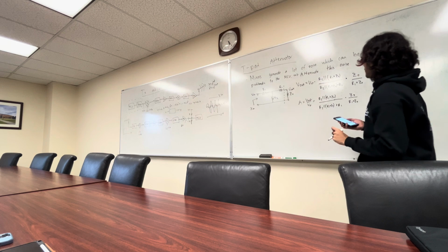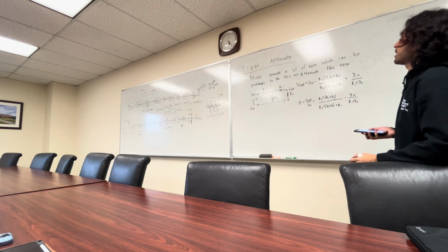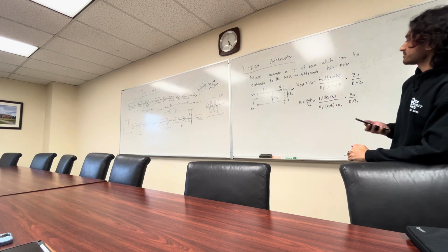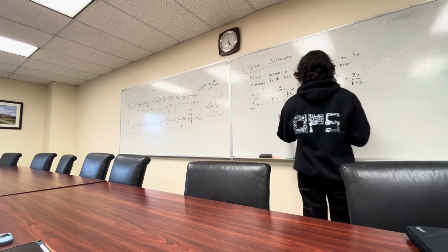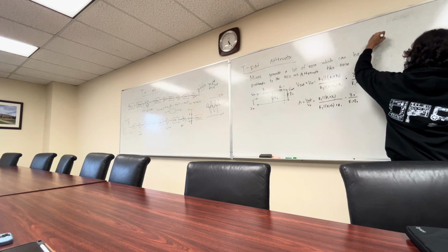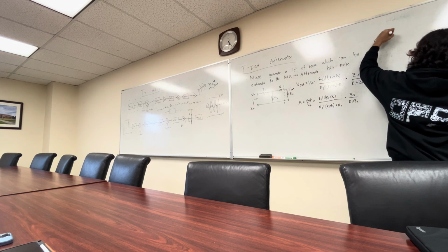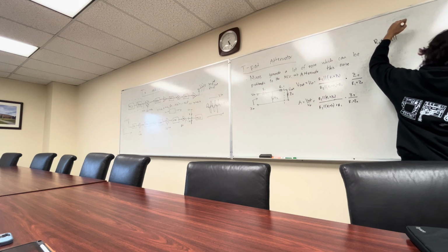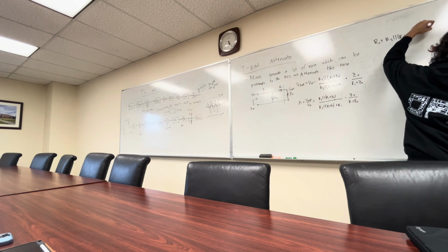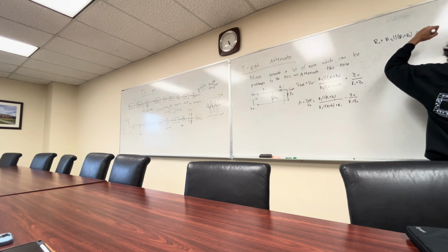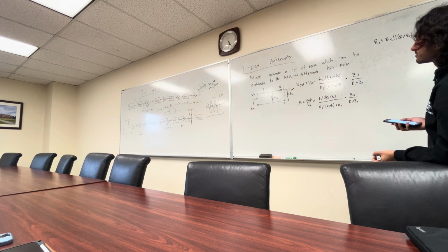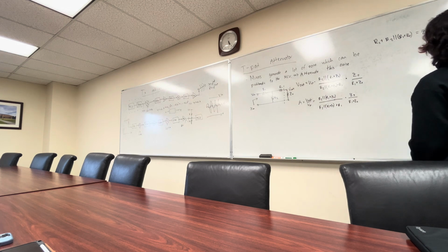Now we want to do impedance matching. At the end of the day, we shove an attenuator in there, and we want to make sure that we can still maintain maximum power transfer. So to do that, let's see what's the best. I'm going to write it up here. 1 plus, this hopefully makes some sense: R1 plus R2 in parallel with R1 plus Z0.